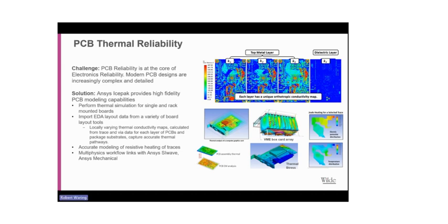IcePack provides a comprehensive solution to address this thermal challenge. It facilitates thermal simulation for both single and rack-mounted PCBs. Whether you're dealing with individual boards or complex server racks, IcePack can deliver accurate thermal analysis. It seamlessly integrates with various board layout tools, enabling direct import of EDA data. This streamlined process saves time and ensures precise representation of the PCB's geometry in the thermal model.